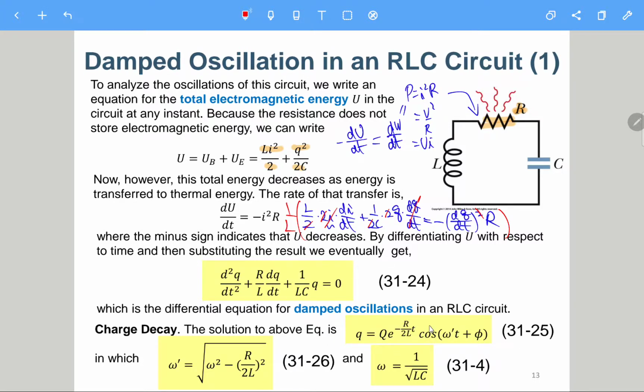We have an exponential function times a cosine of something. And then this cosine argument is not 1 over LC anymore. For this expression here, we have omega squared, which is 1 over LC. But here we need to subtract something, which is not so trivial to you, but we can still derive it.